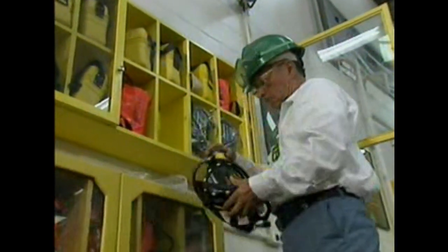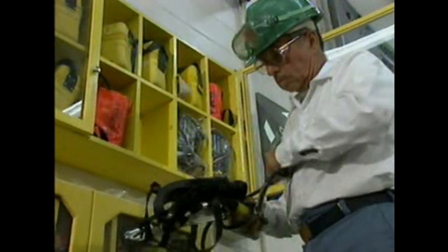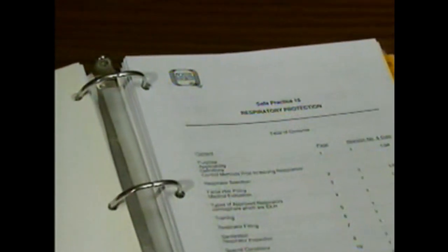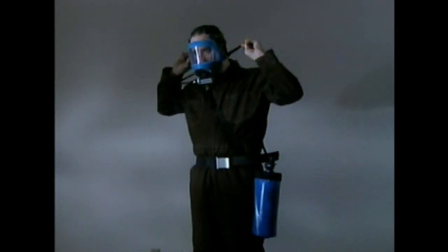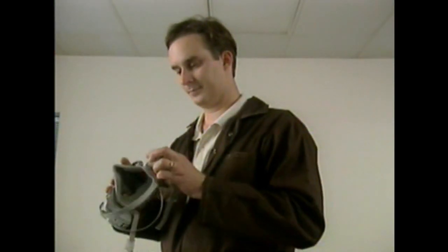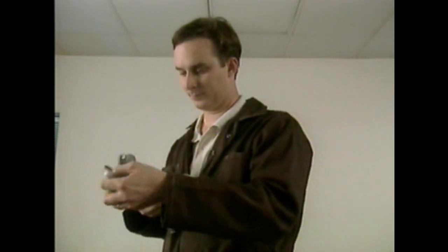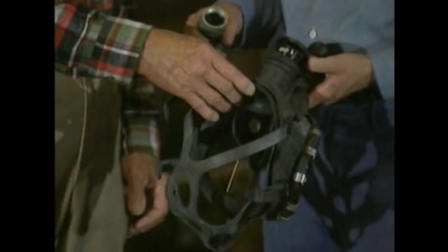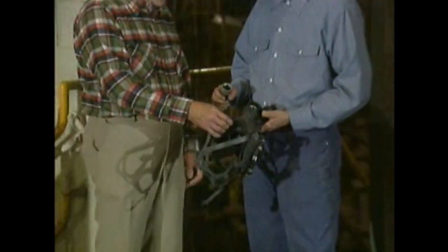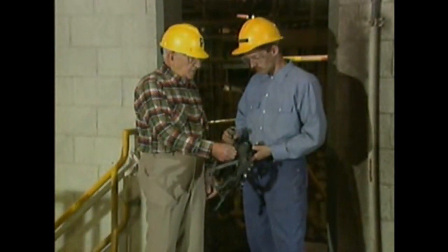Before a respirator is used, it must be checked for good condition and proper fit. Employers are required to establish procedures for fitting employees with respirators and procedures for testing the respirators. The employee's responsibility is to follow the fit test procedures each time the respirator is put on. Generally speaking, each time you put a respirator on, you should check its condition. You should always examine the straps, sealing surface, and gaskets for any cracks. If a respirator isn't in good condition, don't use it. Follow your facility's procedures for reporting damaged equipment.